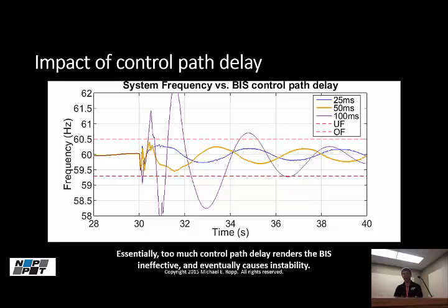It couldn't recover the steady state. So you have to pay close attention to the design and the implementation of the controls. It's not just the software. There are also practical applications like control path delay. Remember, the delays include the filtering. There's all kinds of signal filtering in there too that has to be considered as a part of the delay path. So we've already hit most of these.